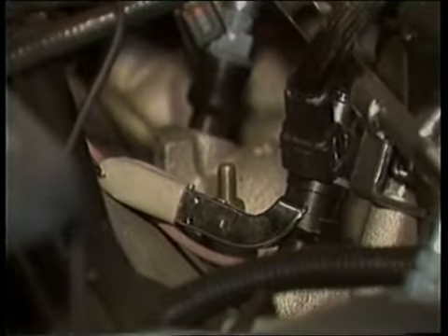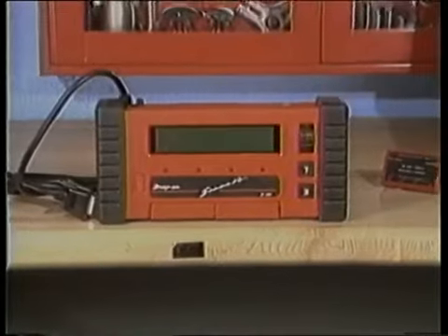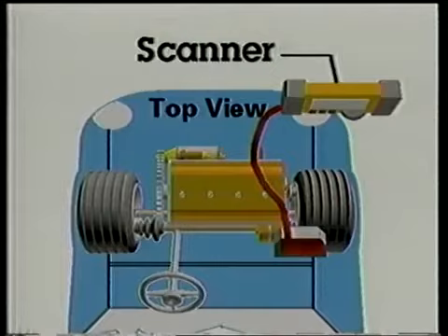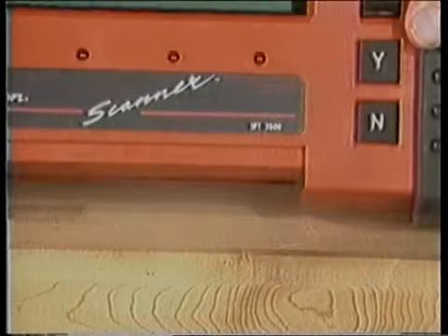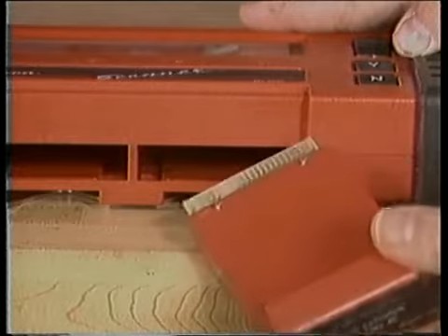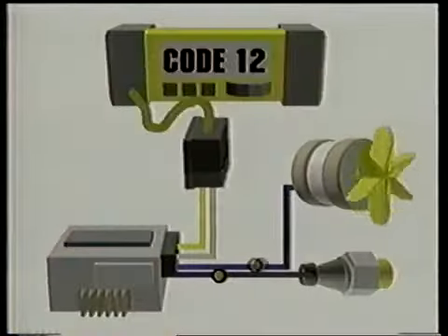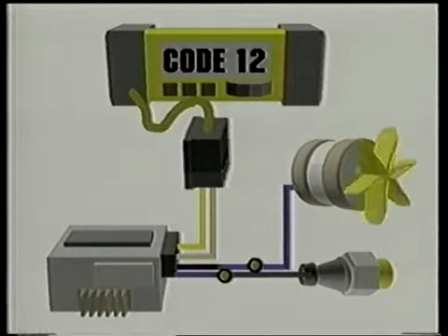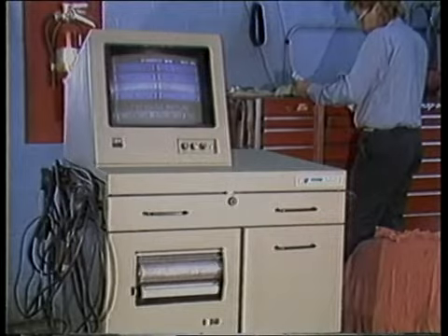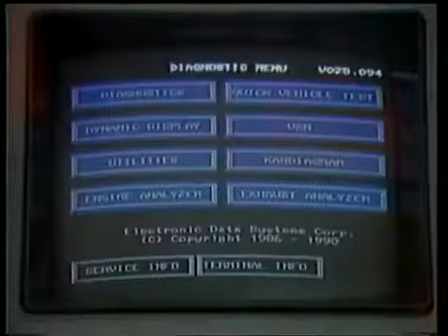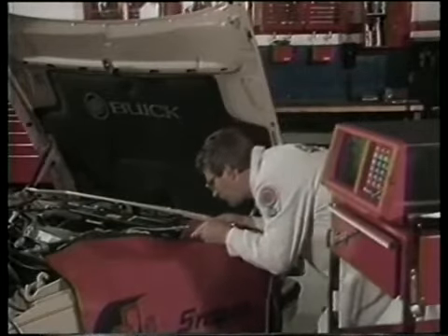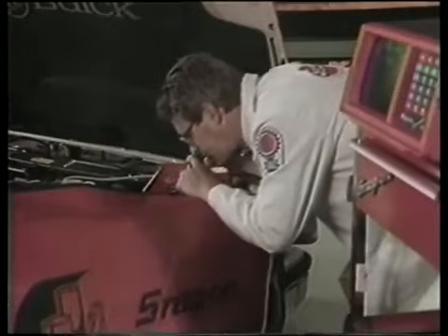In other videos, you learn how to use computer self-diagnosis and scanners to find and correct electrical problems in computer-controlled engine systems. For example, a scanner will quickly indicate failures in a specific circuit. You would then know to test a component in that circuit. This provides a quick and easy way to find electronic components that have failed in an electronic fuel injection system. Large analyzers can also be used to troubleshoot the electronic components in a fuel injection system. Keep in mind when troubleshooting that conventional problems, fouled spark plugs, open spark plug wires, and conventional troubles may seem to be caused by the injection system.